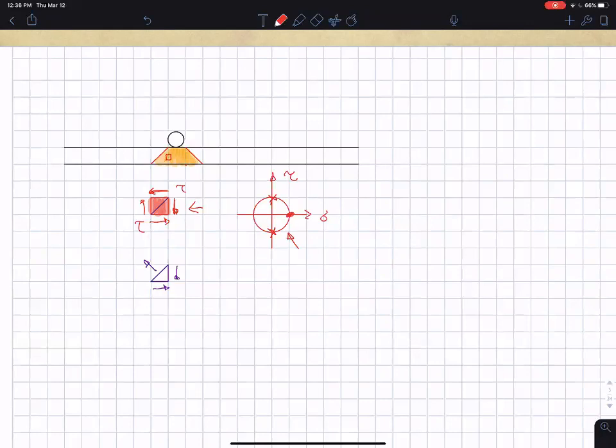The Mohr circle is centered around the origin. And so you can see that if that's the shear stress, that's the radius, so that stress would be tau 0. The key thing in this is that the angle to the principal tension axis on the Mohr circle is 90 degrees. And remember, 90 degrees equals 2 theta. So in real life, the angle to the maximum tensile stress is 45 degrees. And that's what this is. You'll see a 45-degree cone pop out.